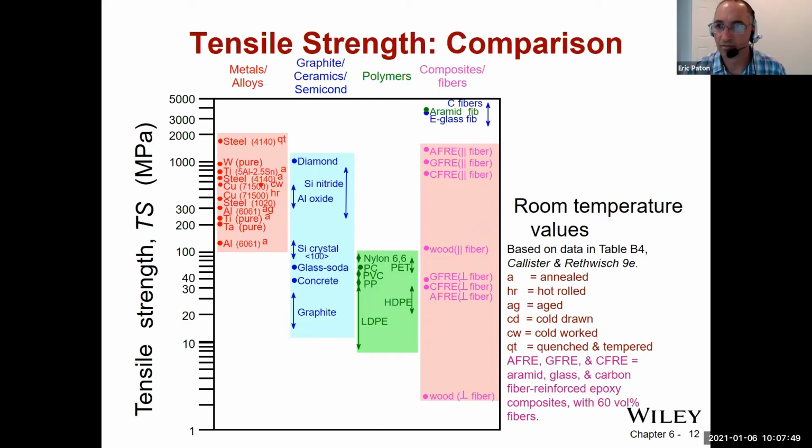So you might be able to identify, based on the Young's modulus, which one is the 2000 series aluminum, which one is the 6000 series aluminum, and which one is the 1000 series aluminum. Those are the three different types of alloying aluminums you're going to see here. And based on the tensile strength, you might be able to determine if this one, for the 6000, happens to be aged, or is it just annealed.